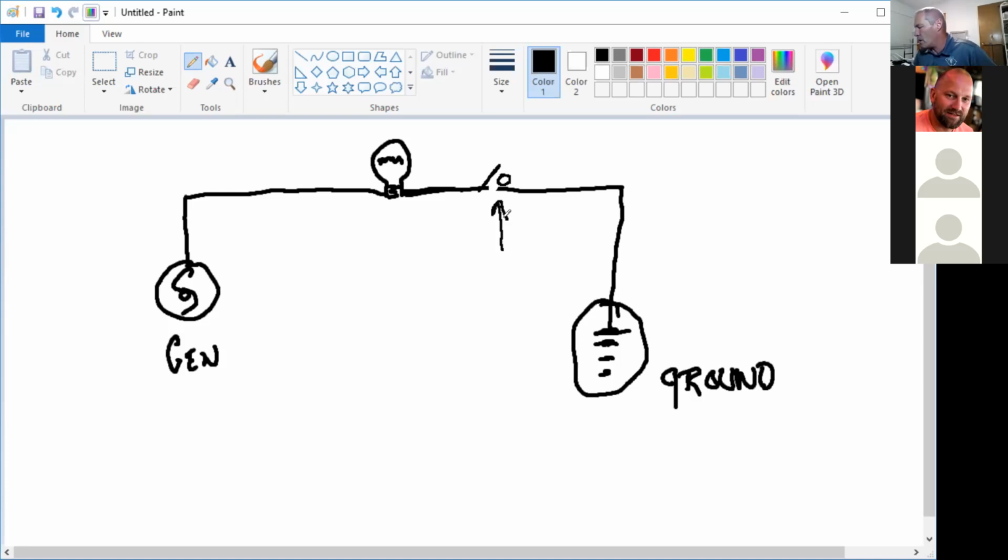All right, that's something you're going to need to remember out there in the world. And when we talk complete path, this has got a lot to do with the safety of your work and how electricity works out there in a system, in a utility system. So anytime that I break the path, no matter where it's at in my complete circuit right here, current will not flow. So let's back up just a moment.